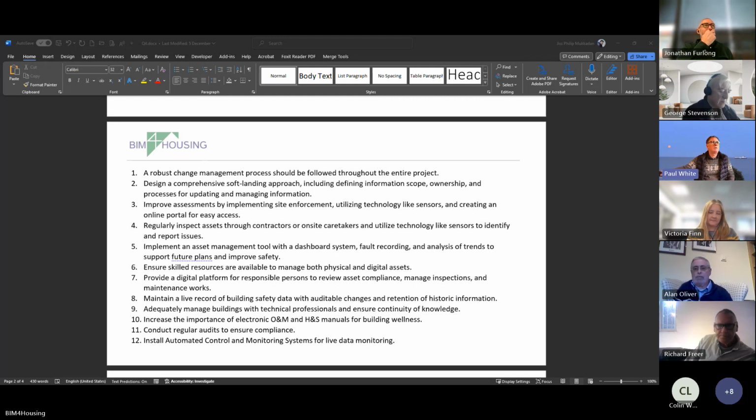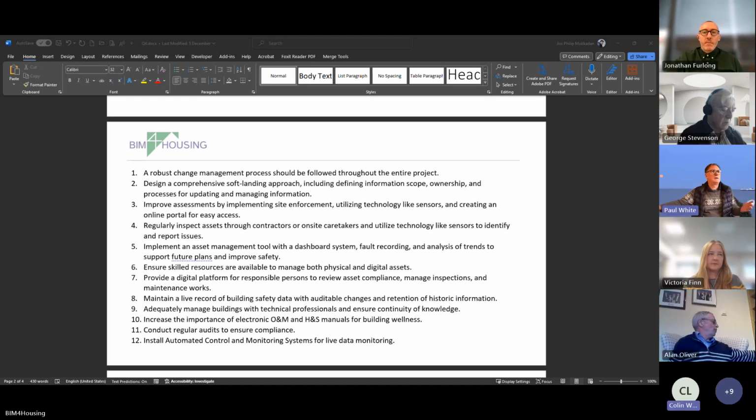But in terms of what you're saying isn't covered, Johnny, in which document? So smoke control, fire alarm systems, and anything under etc. are all covered in BS 9999, which is referenced from BS 9991, the management of apartment blocks. And it is very, very clear. Look at Annex I, and it tells you very clearly what you have to do daily, weekly, and monthly. And this is the point.